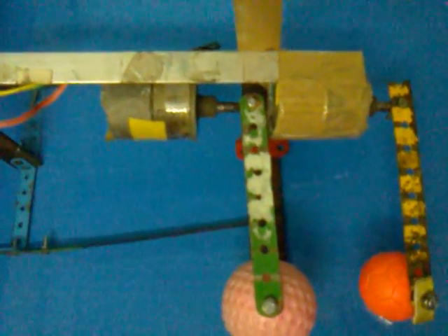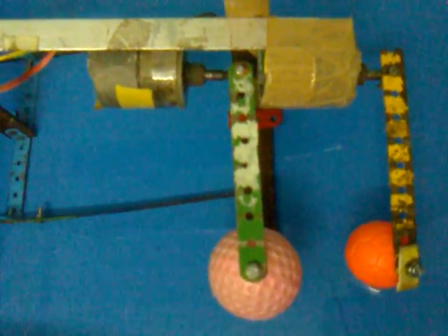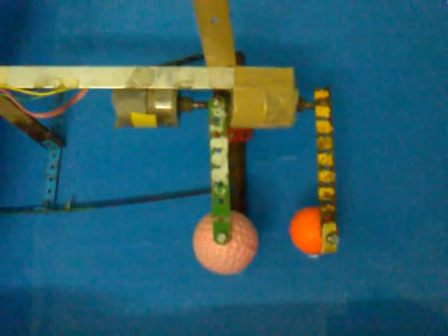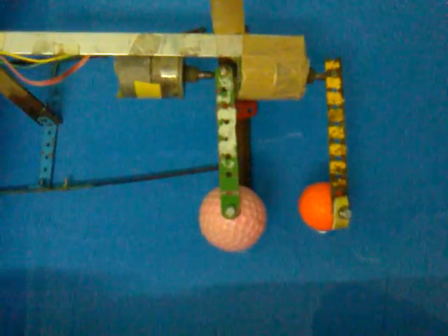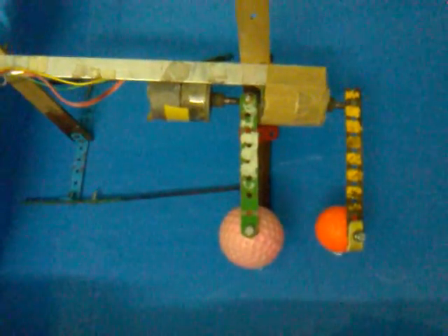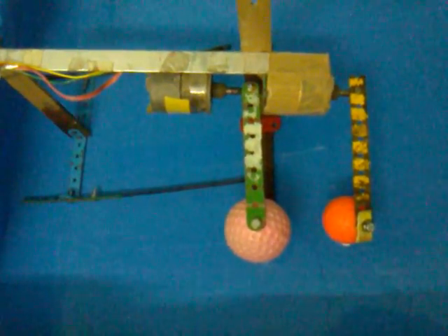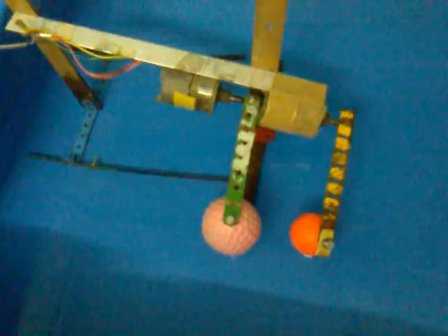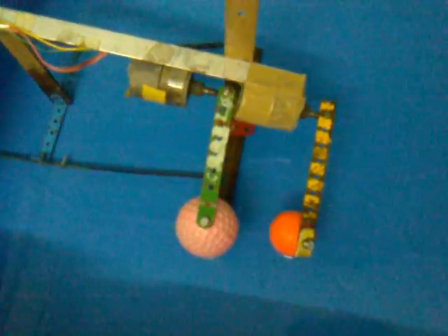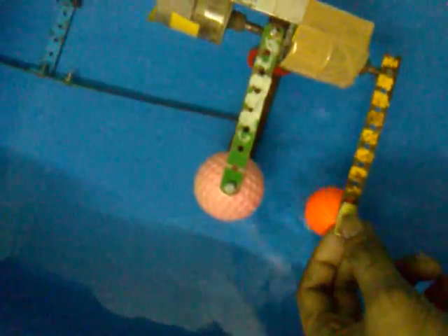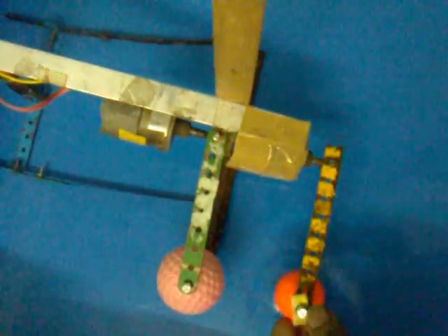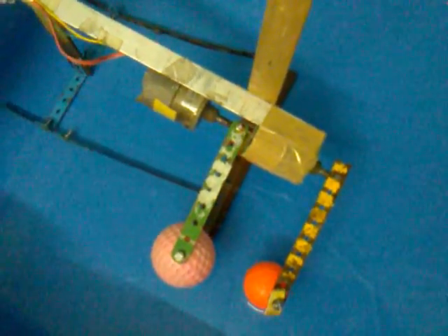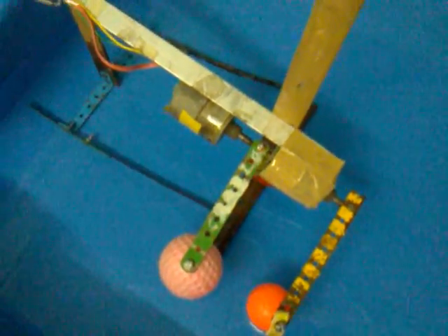In a traditional turbine, the higher the wave displacement, the larger the output. This leads to inconsistency at the voltage level. So, this design works on the principle that every inconsistency is a short harmonic of a very large consistency. And so, instead of directly driving the turbine, the float, when it rises up, first pressurizes oil in a pressure tank, and this pressurized oil will then drive the turbine at a steady uniform rate, giving a steady output level.